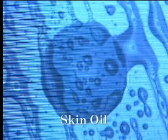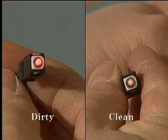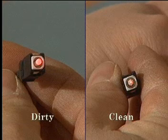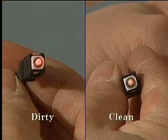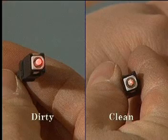Dirt, thick residues, and other large contaminants will be easy to see. However, fine residues from water and oils may be more difficult to find. Fine residue can be detected more easily by the use of a small visible laser. When the beam passes through the connector, residue will severely scatter the light, causing the ferrule end to glow brightly. A clean connector will exhibit very little scattering.